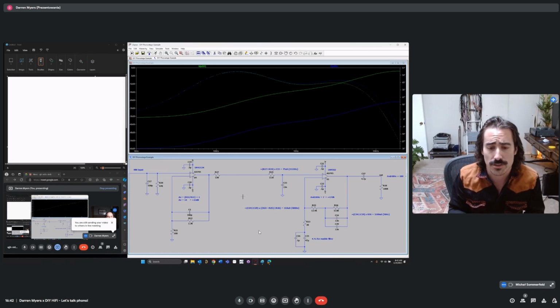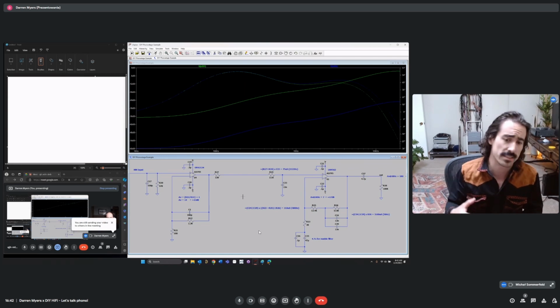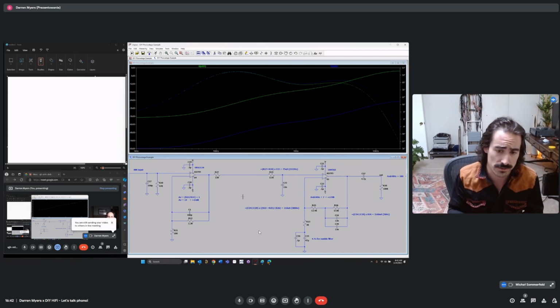So you can actually hear RF when it's getting hit with electronics that are being slew rate limited. Maybe people listening have run into a situation where tube amplifiers have picked up radio stations, or phono stages have picked up RF noise or radio stations, and this is the reason why they would do that, and the reason why we would have C1.